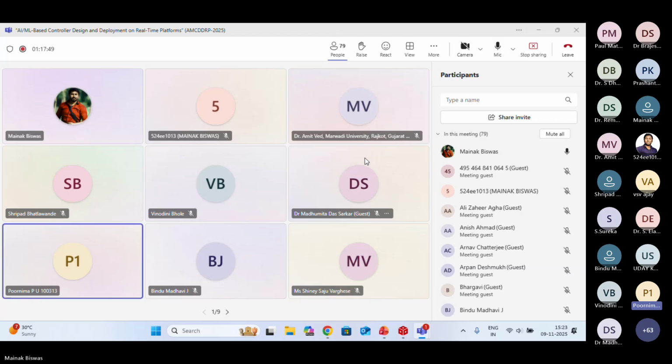Actually, we write coding in C using the C program itself. So we give pin numbers and all, like the PWM input signal and output signal, where it has to enter and leave, through which pin we define through the program. Isn't it, sir? Yes. In my case, I am using the C2000 launchpad. The pin diagram is different for my case. If you are using another version of the C2000 launchpad, the pin numbers will be different. As per your launchpad, you can define your pin numbers.